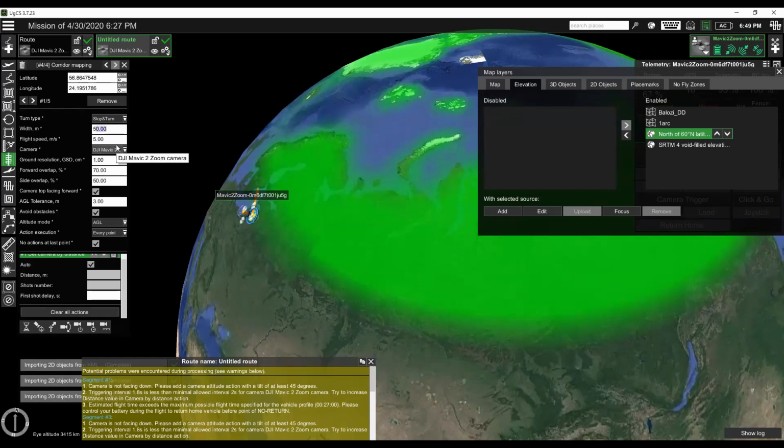The question: why don't you use a specific takeoff and land tool? I can't actually explain this. I'm simply used to flying with quadcopters, and in such a case I do not need to use a specific takeoff. I always place the first waypoint near my takeoff location and just start the route. The land tool you can use if you are 100% sure that you will want to land when the route ends.